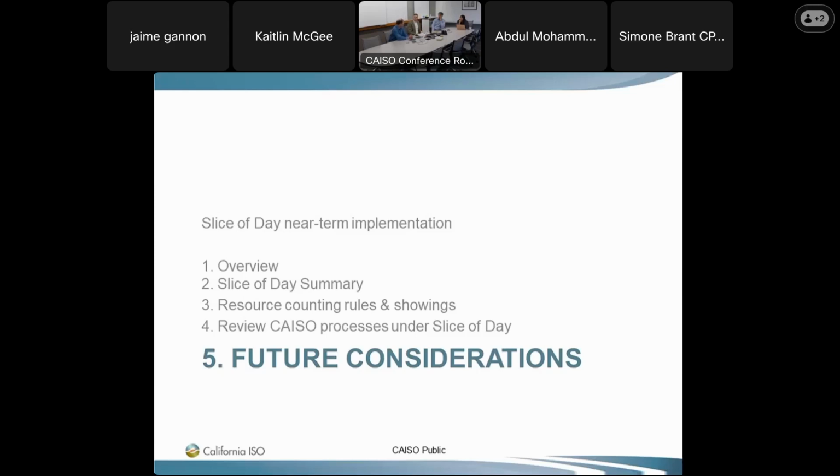And one of the other things, given the earlier discussion, that I wanted to point out about the slice of day PRM: Noah is correct that, of course, the CPM depends on accounting conventions, but at the end of the day, those PRMs coming from the CPUC are all determined by what is adequate to hit that 0.1 LOLE. So I don't really see that as implicating a reliability concern, because if all the modeling is accurate, and of course modeling is always inaccurate, it's just a question of how inaccurate, it should result in a planning reserve margin that's appropriate for the accounting conventions and the QC values that you're getting.